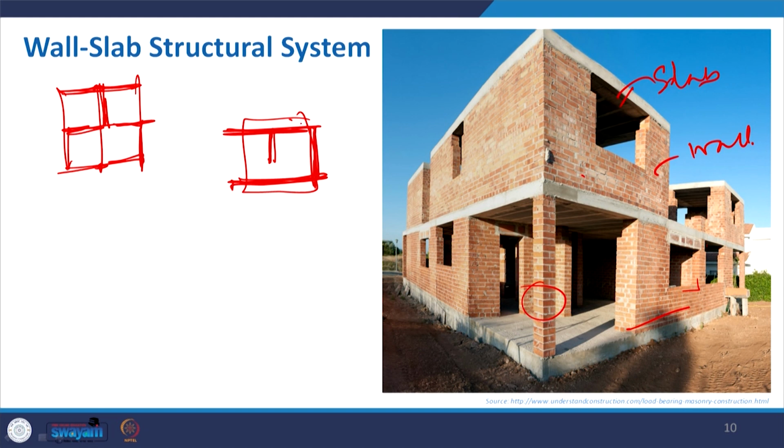Looking at the span, we have to design accordingly, and again that has some restriction, because when you go for this load bearing structure, heavy mass will be imposed, and there is a restriction on height as well. There are studies where we have seen that with proper treatment it may go higher, but normally we can't go for a high rise building, because this arrangement will not really work with all the imposed loads.